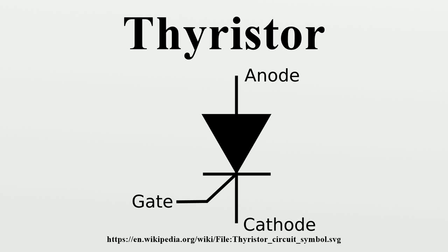A thyristor is a solid-state semiconductor device with 4 layers of alternating N and P-type material. It acts exclusively as a bistable switch, conducting when the gate receives a current trigger, and continuing to conduct while the voltage across the device is not reversed.